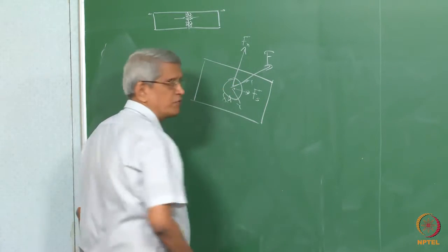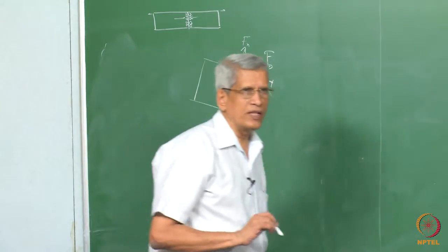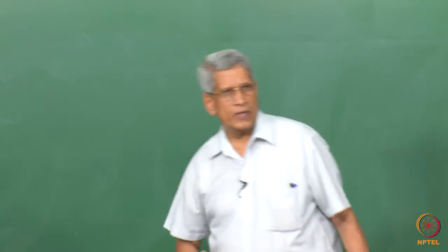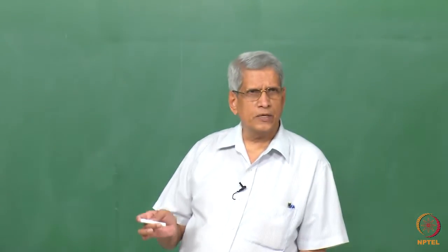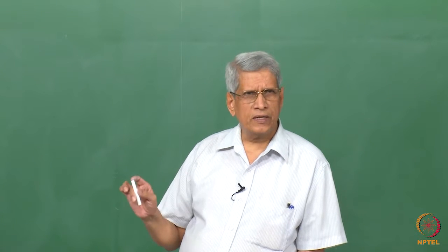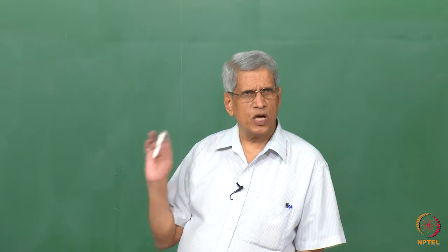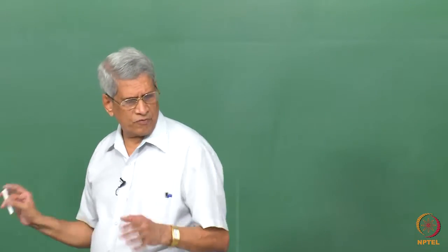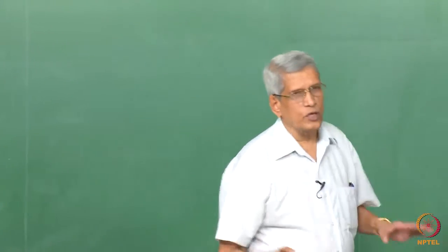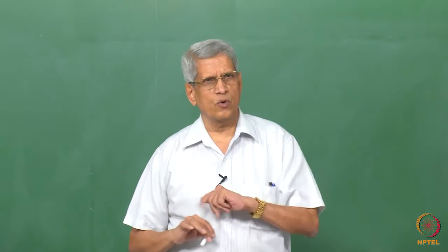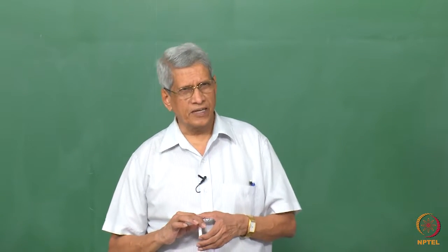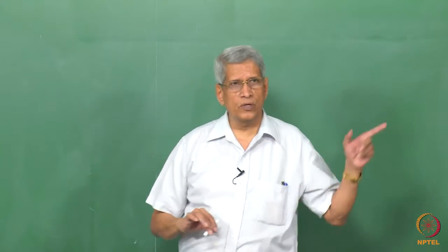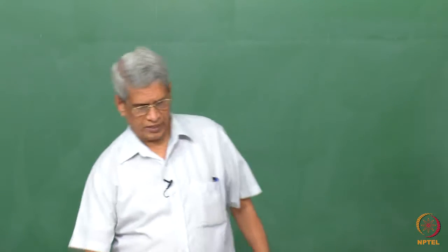That is, at this point when we are trying to measure the net force which is being applied, that can be separated into components along 3 surfaces passing through that point which are perpendicular to each other. Considering those 3 surfaces is equivalent to considering a Cartesian coordinate system and defining the stresses, correct? That is what is being shown in this slide if you look at it.